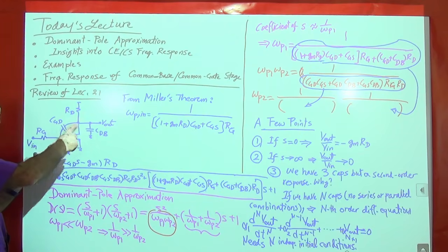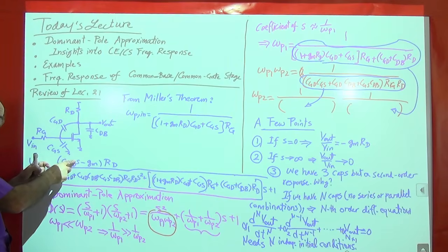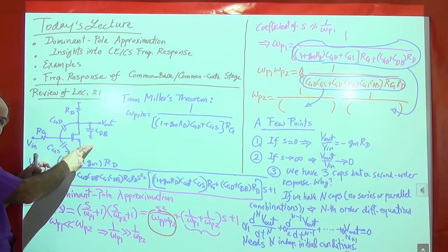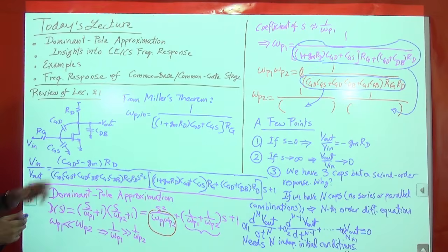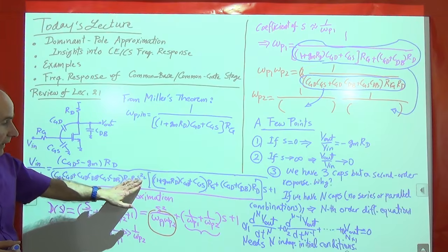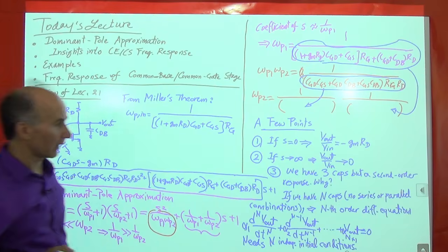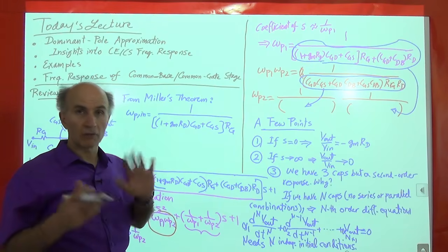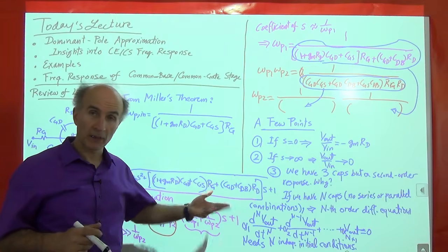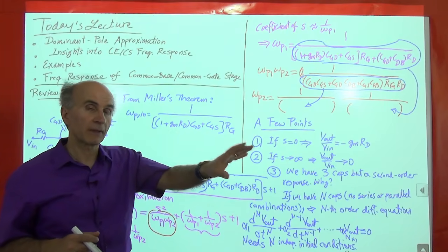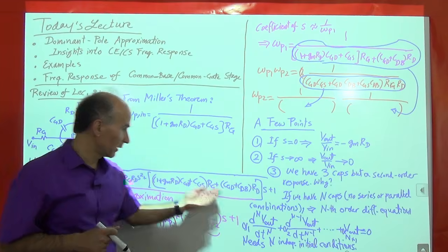We say these capacitors form a loop. Because they form a loop, one of the initial conditions is removed. We have only 2 independent initial conditions, right? If I have this, I have this, and so on. So it is because of that that this system reduces to a second order system and is not a third order system. Okay? All right, so that's just a point of curiosity. If you're not interested, don't worry about it. But oftentimes that is also helpful in predicting what order the system will have even before we write out everything.